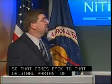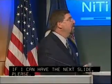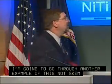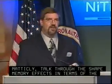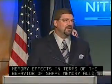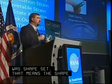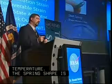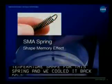If I could have the next slide, please. I'm going to go through another example of this, not schematically now, but talk through the shape memory effect in terms of the behavior of a shape memory alloy spring. So first of all, you have to realize that this spring was shape set. That means the shape for the spring was set at a high temperature. So the spring shape is the high temperature shape for the spring, and then we've cooled it back down through room temperature and formed the self-accommodating martensite.